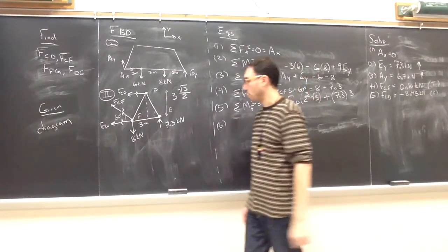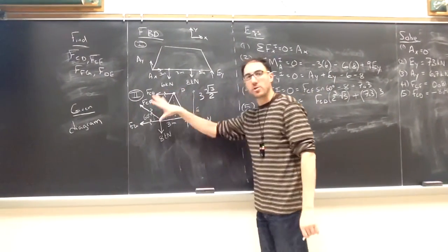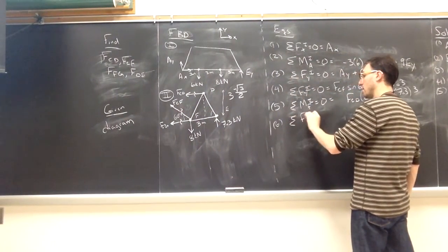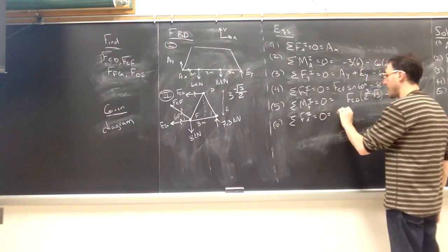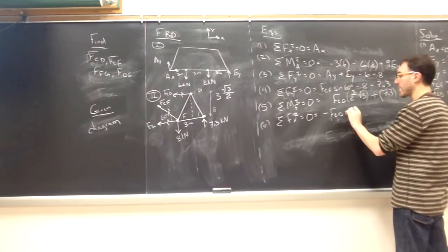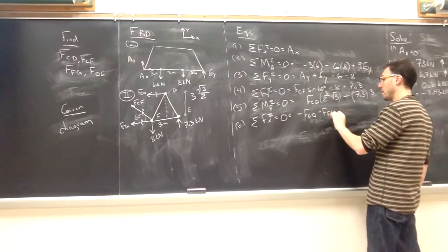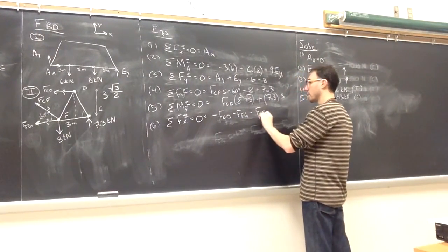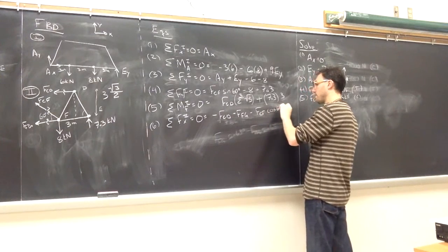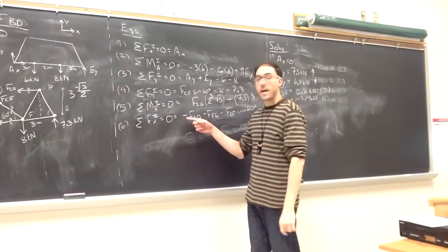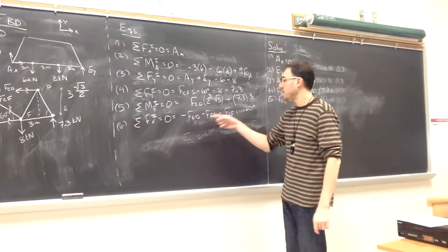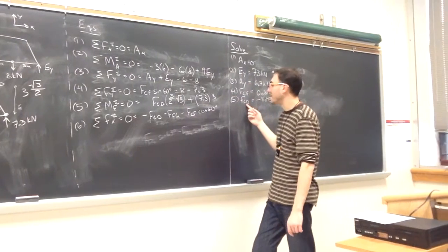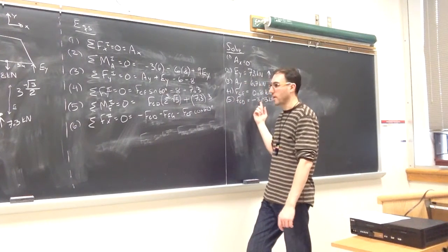In the x forces is where we have to be careful that we're writing the equation based on the picture, with a negative FCD, a negative FFG, and a negative FCF cosine 60. Now here again, based on the picture, these are all negative. They all point to the left. But it did turn out that my CD value was negative, or in compression.